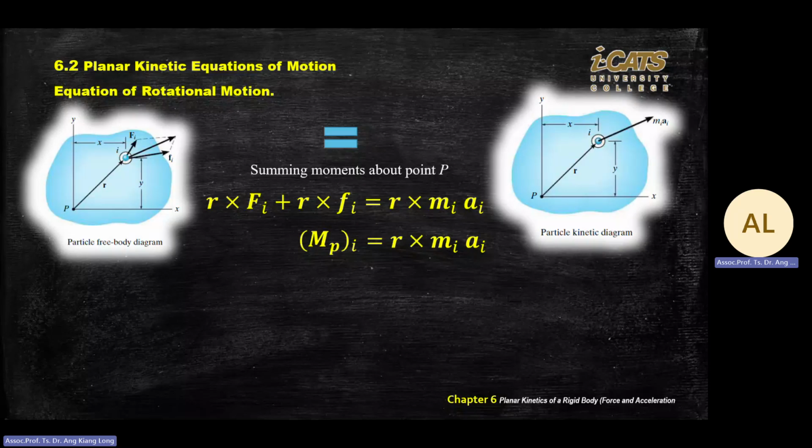So if you put this force into x and y, so this force in x direction, what is the perpendicular distance? Here, y. And then if you break your force in y direction, what is your perpendicular distance? This one. So you have two moments, one from the x direction force and one from the y direction force. Okay, this is on the left hand side. And then right hand side will be your MA point.